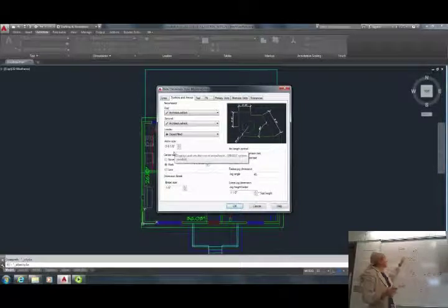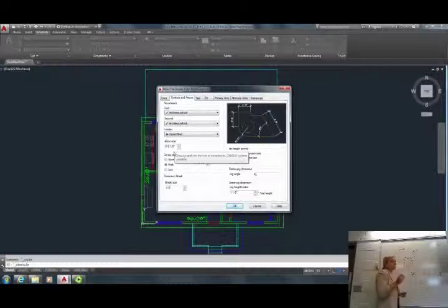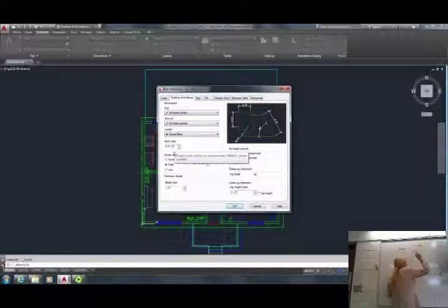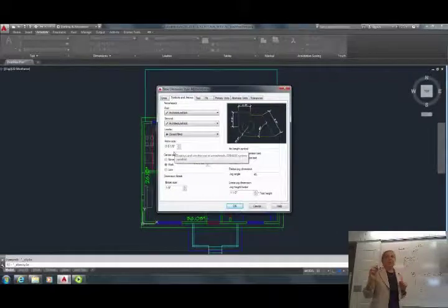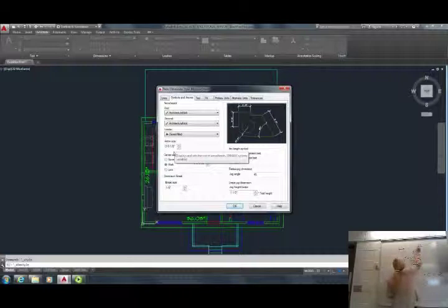So for my drawing, I would say probably I want it again 1/16. I'm actually going to type in 1/32 for my tick, because this is the point and this is the size of the arrow, but when you do tick, it still measures it from here to here. So I'm going to make it half of what I actually want it to be, I think. Well, we can test it whether what we're getting is this.